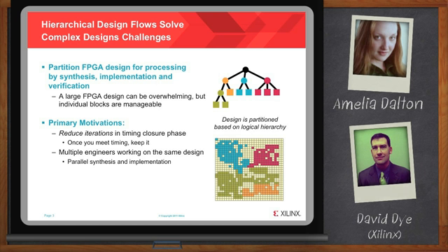So, for example, if part of your design is a high-speed memory interface or a piece of time-critical IP like a PCIe core, you can use a partition to isolate its result. Once you achieve the goals of that particular module, any type of change to the rest of the design will not undo the validated results for that critical partition.